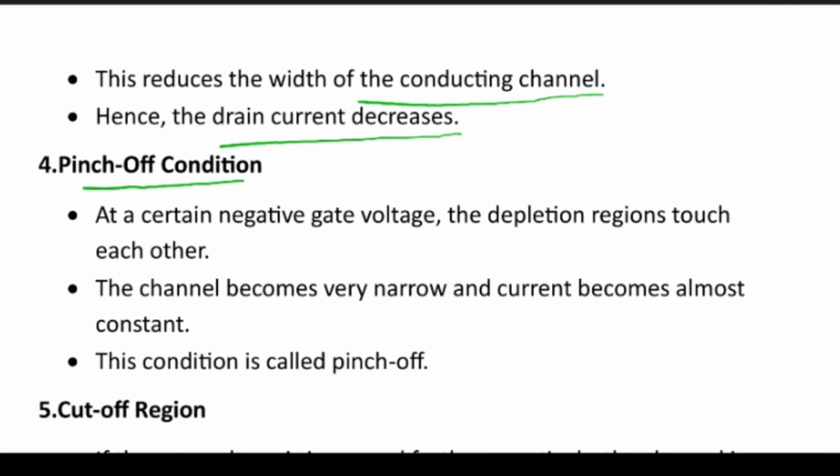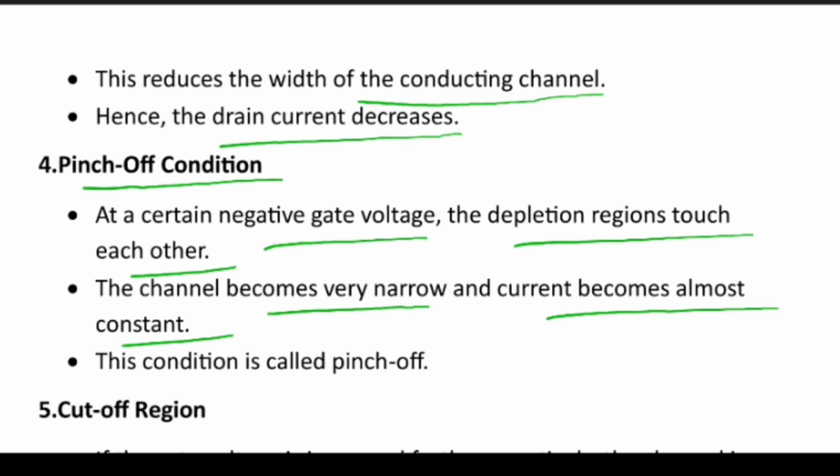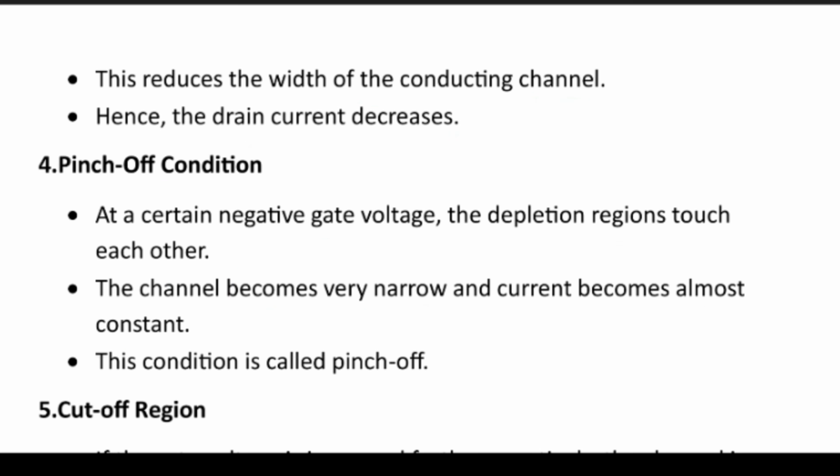Next is the pinch-off condition. At a certain negative gate voltage, the depleted regions touch each other. The channel becomes very narrow, and the current becomes almost constant. That condition we call pinch-off.